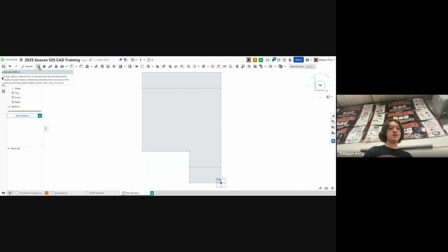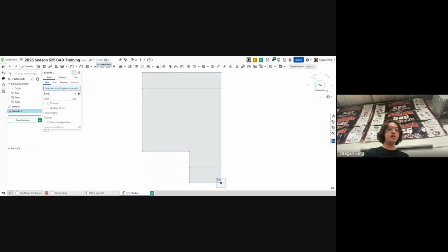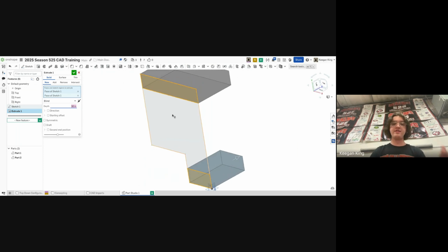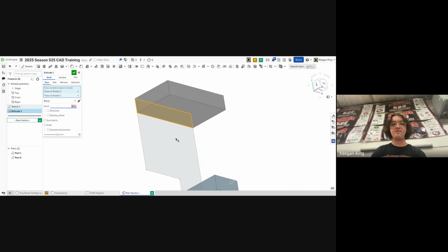Then I'm going to use the extrude tool, clicking it up here, or you can use Shift E to begin extruding. Are these two the same? Yep. All right, so I'm going to start with these taller rectangles right now. And at first, it'll give me 2 separate parts, but that's okay. I'm just going to put in 30 for the depth here, and then we'll make these 2 rectangles 30 inches tall.